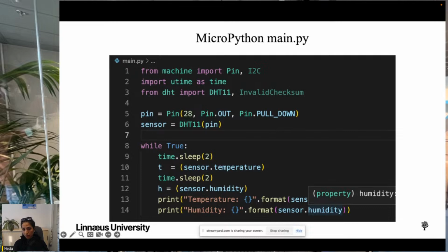When a pin is not being actively driven, it is left floating and can be susceptible to noise or interference, which can lead to unpredictable behavior in a circuit. To avoid this, we can enable a pull-up or pull-down resistor on the pin, which will ensure that the pin is held at a predictable voltage level when it is not being actively driven.